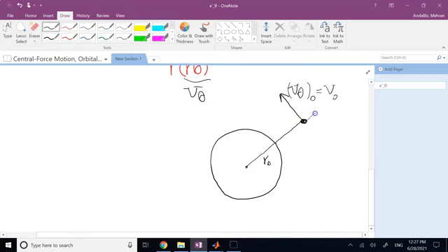And there is not any v_r at time 0. So when you put it in the orbit, you're not giving it any further radial speed, because if you do, then it means your r0 is not going to be constant, and after a fraction of a second you are going to get a bigger and bigger radius. So all you do, your launch velocity that you use to determine the shape of the orbit, is going to be only in the theta direction, not in the r direction.